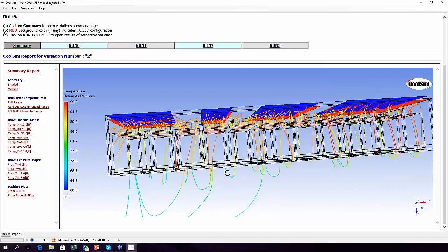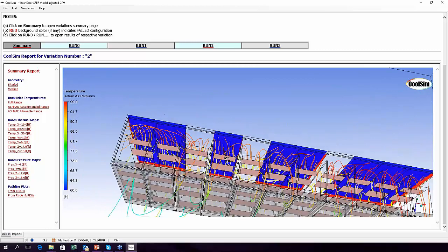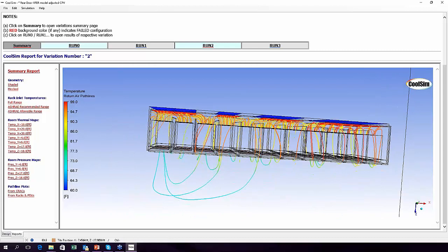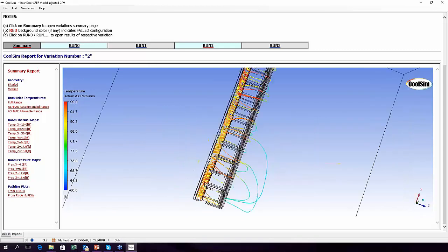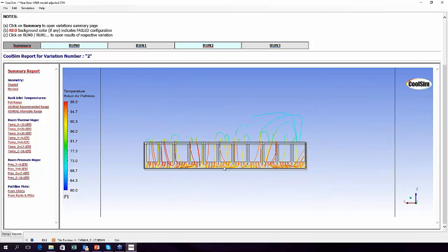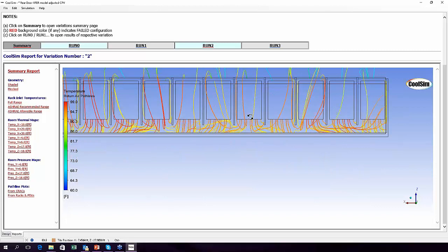So the point here is that you need to understand the failure mode conditions of these kinds of devices and what happens if one fails. As you can see in this design, what we did, again, let me use keystrokes. I'm going to do Y and then N. In this design, what we did is we allowed the air to go from the one that hasn't failed over to some of the others.